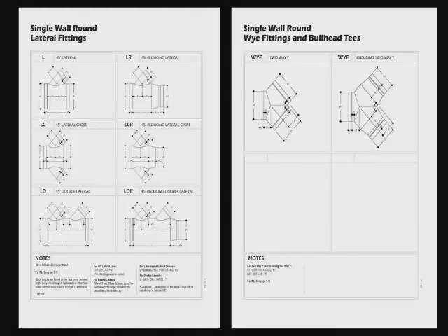We were talking a little bit earlier about the fittings. The laterals come in at a 45-degree angle rather than a straight T. Again, it's a much smoother transition for the airflow to make that turn. Same thing with the Ys. We're meeting at more of a 45 or a 90-degree included angle, which makes it a much smoother transition for the airflow and a lot less turbulence.